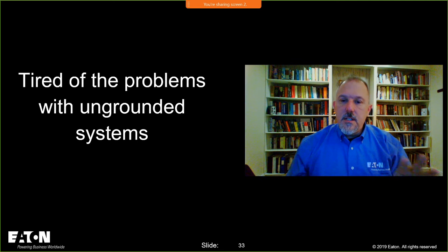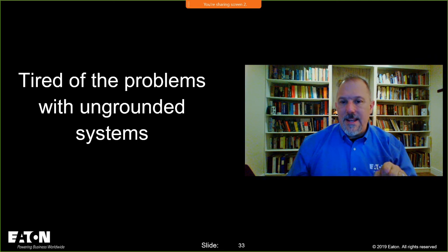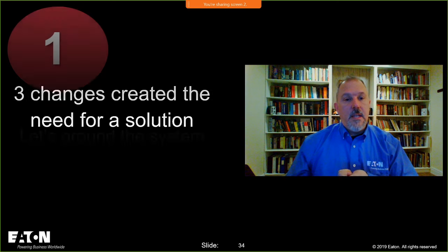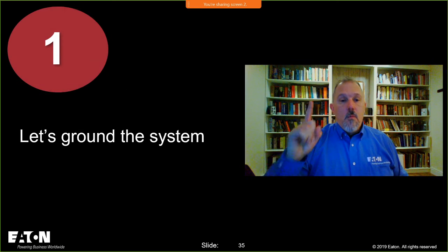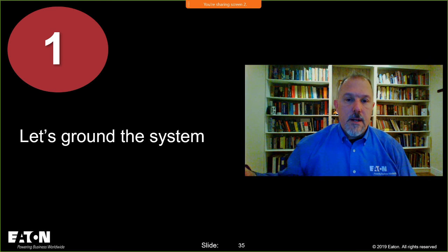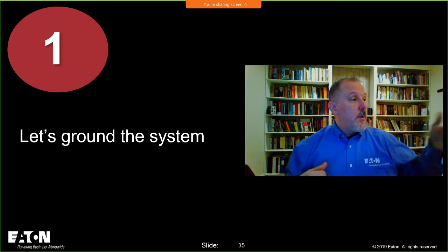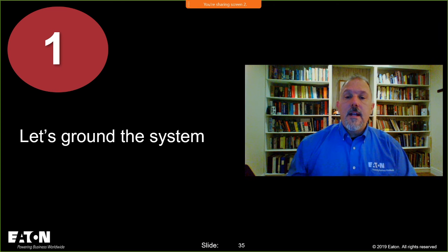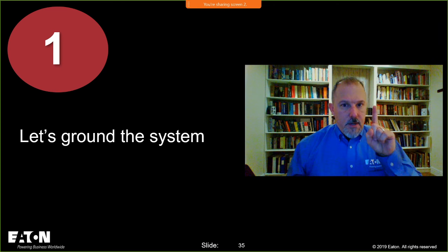There were three changes in our electrical history that caused the need for GFPE. One is we said, we don't like these ungrounded systems. Why? Because with ungrounded systems, I have voltage fluctuations, I'm burning up motors, I have all these issues in my power distribution system because I'm ungrounded. And so they said, let's ground it. Opportunity number one for GFPE.